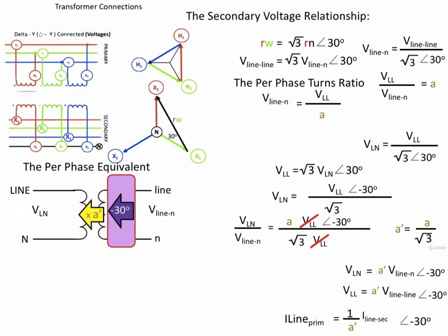In other words, it'll be the inverse of the voltage for the magnitudes, because if we added a purely resistive load to the transformer, it wouldn't make any sense if the current was at a different phase shift than the voltage, because it doesn't change from the voltage. So really this just establishes the fact that the phase shift operator in this per phase equivalent circuit is doing the right thing, because if we add a resistive load, the current would be in phase with the voltage.